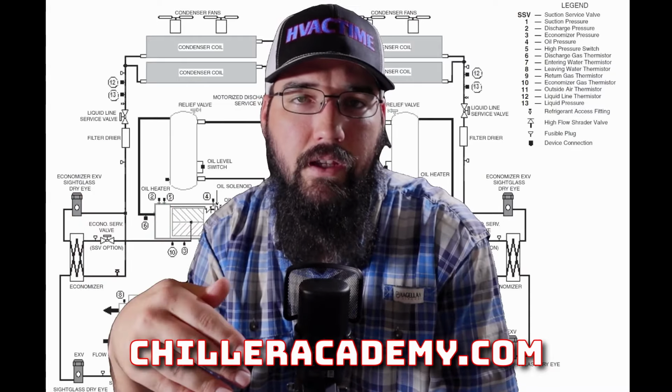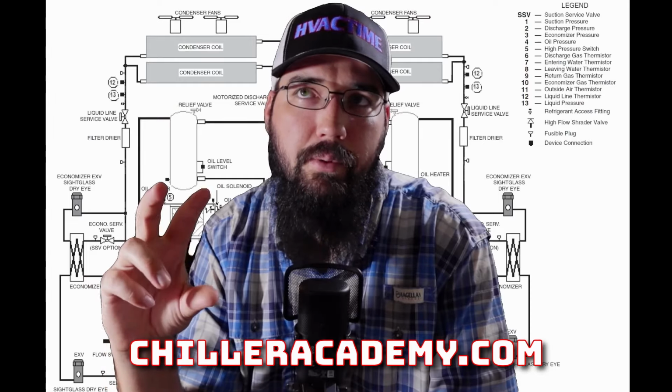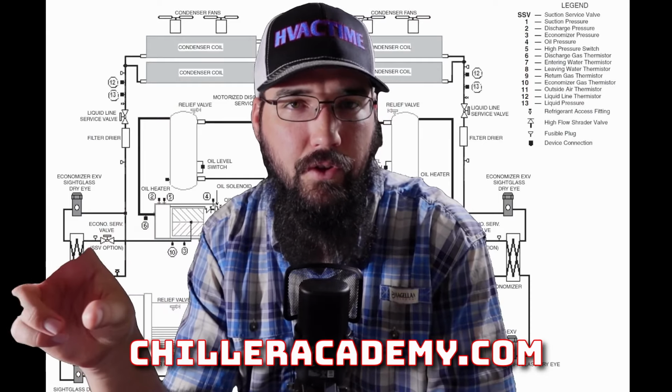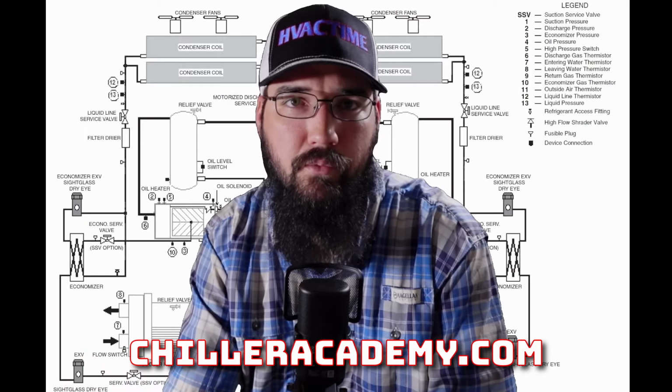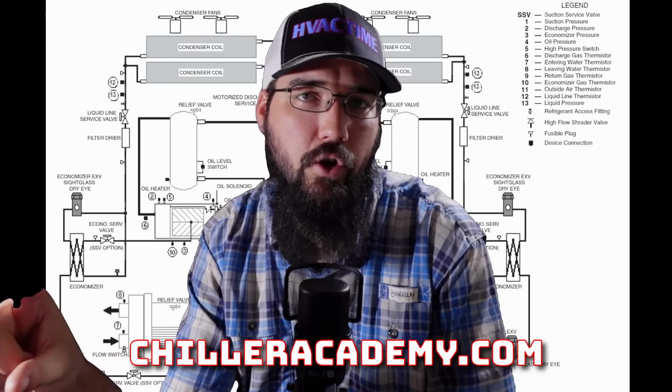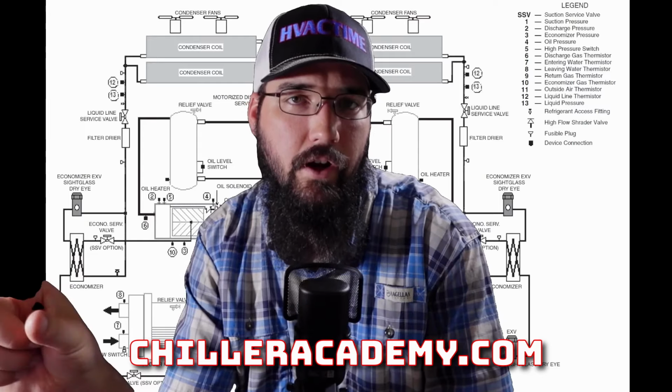Whether it's a slide valve or a VFD, you could replace slide valve with Hertz and think of it that way. Instead of a mechanical valve moving, it's just physical Hertz. Even though our Hertz may not have changed, our amp draw has.